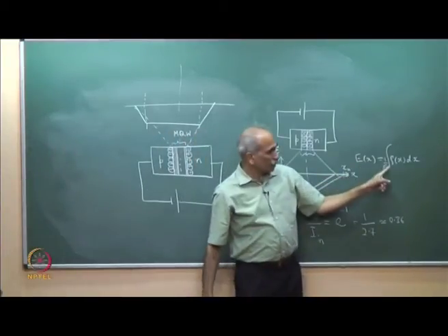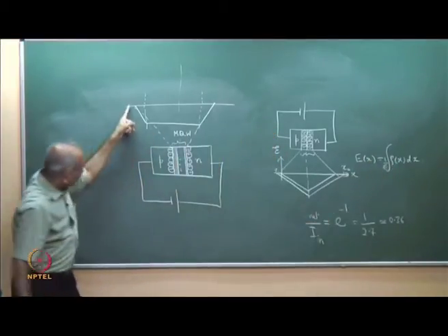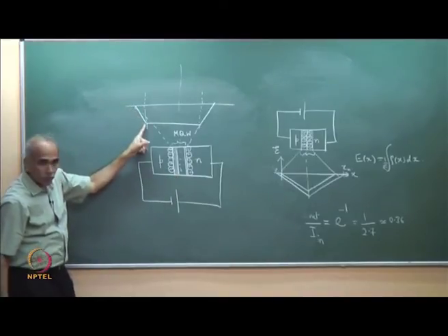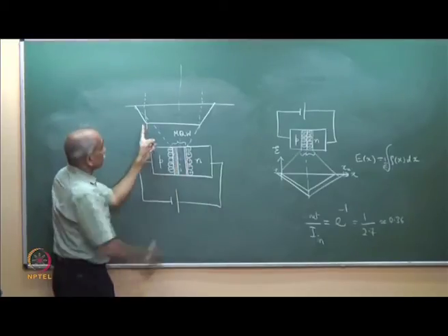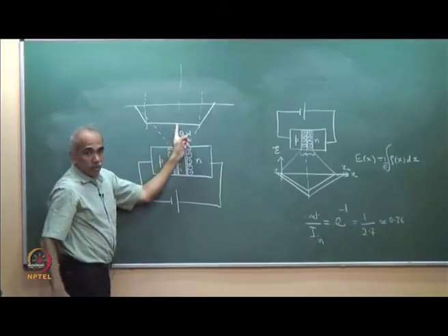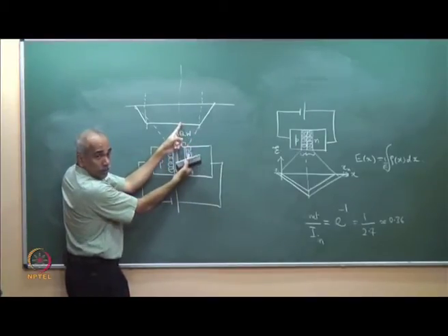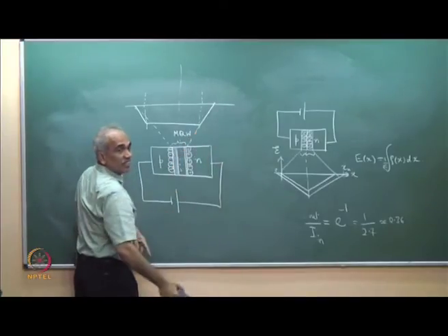The electric field is equal to the charge times dx, integrated. So, you integrate all the negative charges here, and the field increases up to that, with hardly any charges in the intrinsic region, so the field remains constant. When you reach this end, the negative charge is compensated by positive charges, so the sum is decreasing, and the electric field is decreasing.